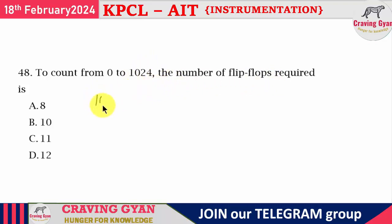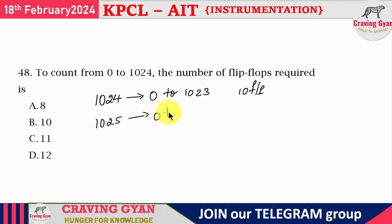To count 1024 numbers, it is going to start from 0 to 1023. You are going to make use of 10 flip-flops. But what they are asking is you have to read 1025 elements, nothing but from 0 to 1024. One extra element you are going to read. So that can be achieved with the help of one more flip-flop, that is option C, 11 flip-flops you are going to use.